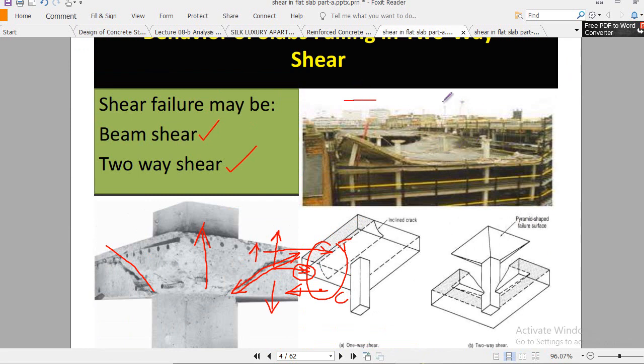For example, you have a beam, okay, and you have a support right here, a support right here, similarly a support right here, and let's say the beam fails at the mid, and a plastic hinge occurs here. So in flexure there is moment redistribution, meaning that this moment capacity is now distributed to this point, this point, and similarly to this point, and now they are taking the loading which is present here.